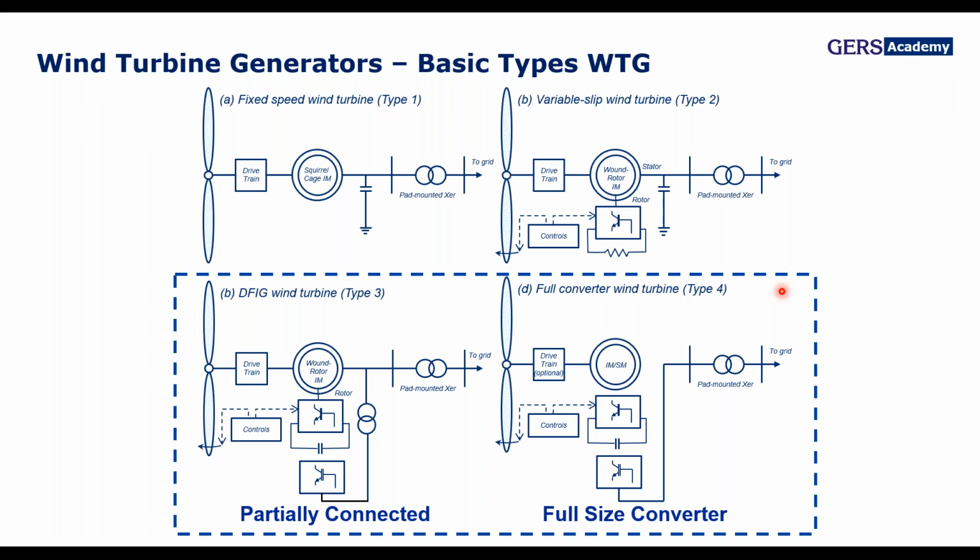So people just started to talk about generic models, models that at least are understandable in the sense that they represent all the different control blocks, and the user has some knowledge or idea about the parameters inside these blocks. I would say that most of the user-written models follow the logic presented in those generic models, but in fact there are some changes depending on the manufacturer and the technology that they are using on the converter.